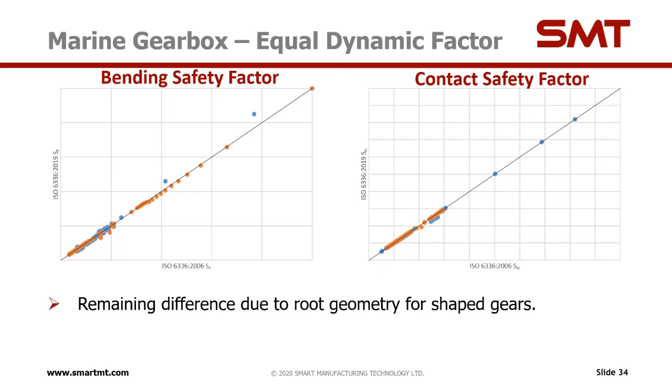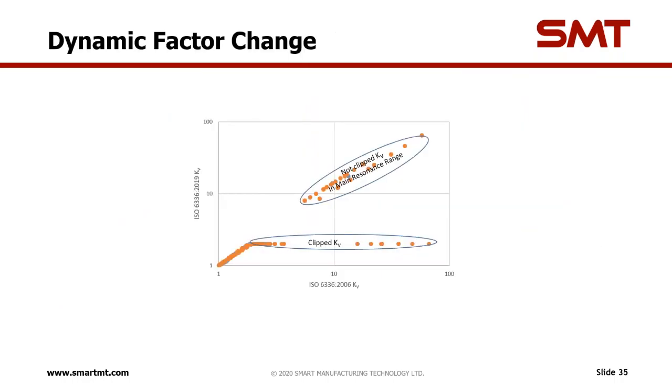There will be a slight variation due to quite low torques and them being different to run analysis, but this slide would actually show the clipping effects in the dynamic factor. So the non-clipped region would actually show a trend which should be one-to-one between the same versions, and there will be a clipped region which is outside the main resonance range.